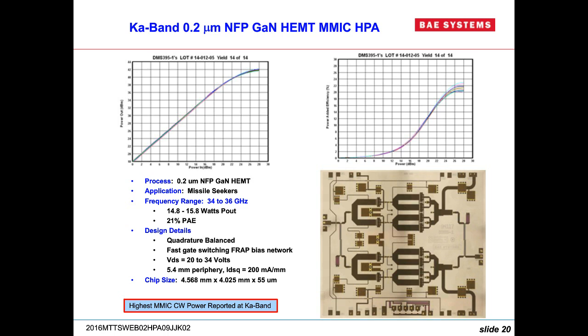I didn't have time in this abridged presentation, but in the full DML talk, I show a spatial combined amplifier that has a tapered waveguide at input and output, and has a connector launch that launches to the modes of that tapered waveguide that combines the output of the spatial antennas, dipoles at V-band in that particular case. But it could be any antenna. It could be a broadband thing like a Vivaldi notch. There's a lot of implementations for the antenna. But spatial is definitely one of the ways to go.